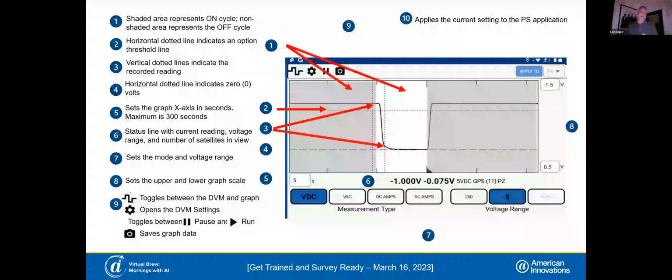Now that off delay, that is probably the one you are going to adjust the most. You're going to walk that out. In this particular case, we'll probably want to walk it out a little bit more to get on our instant off on our flat. We see all sorts of waveforms out there. You can get anodic spikes, and if it's too tight in there, you're going to catch it right inside that anodic spike, and you're not going to get a true instant off reading. We also have a zero line to show you where your 0 volts are.